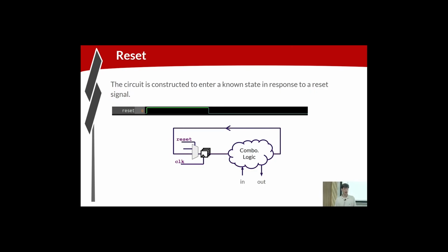Often we use a negatively asserted reset signal, reset N or reset bar, or whatever you want to call it. That's kind of arcane based on, I don't know, historic constraints. With TL-Verilog, with makerchip, we use a positively asserted reset, design all our circuits that way.